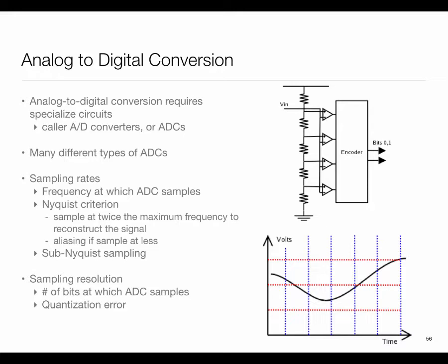Let's take another example. Let's say I have temperature which is changing at some rate, or some signal which is varying. And again, if I were to reconstruct, you can use Nyquist. But if I were to say give me the average over it, you can do statistical sampling over it. You don't have to do Nyquist rate sampling. So designing with sensors, that's one part: what rate you are going to sample, what is the strategy for sampling.